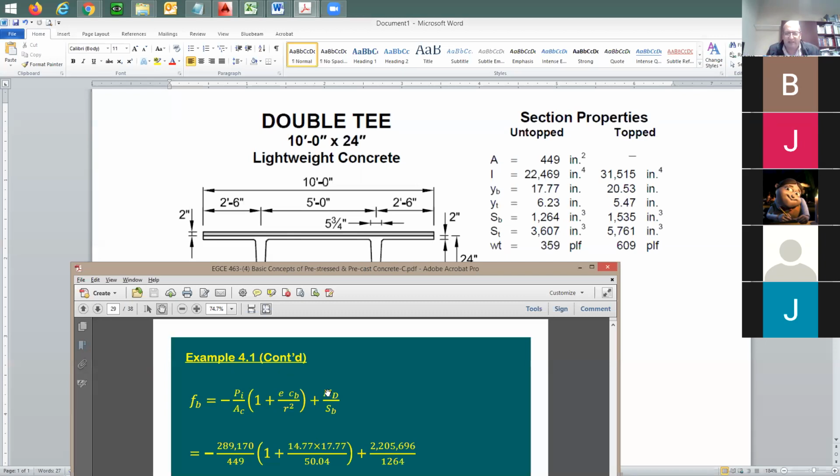Do I have additional dead load yet? Do I have concrete topping yet? You say no, nothing yet. All right. So I'm going to take it, put it in the building. What loads do I have applied on it? I'm going to have here PE as a compression force, pre-stress. And when it comes to the applied load, I'm going to have only self-weight. I didn't do anything yet, correct? So this equation seems to be good, but instead of PI, I'm going to put here PE.